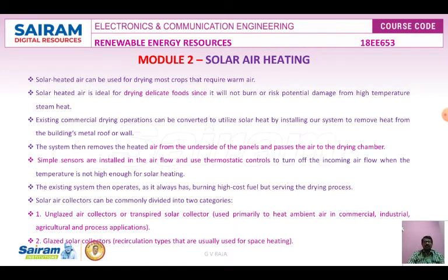In many cases we need only a confined area with direct flow of airflow. If you have a sunny window, that means a window facing the sun, you can put a piece of black fabric or wood or plastic material against the window frame, and you can trap the air in a short period of time. There needs to be a space between the black material you choose to use and the glass window pane itself.